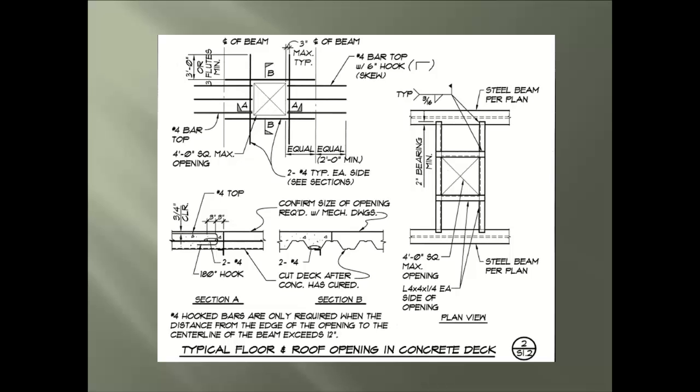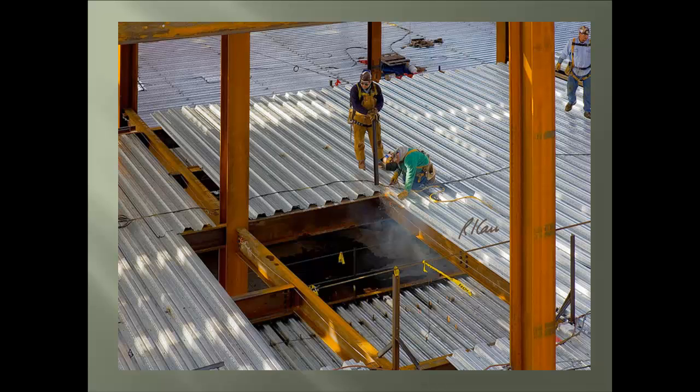First, we see the universal sign for openings through something, which is the X. Next, with this opening, there are the 2 steel beams and the steel angles used to make the actual opening. The next material is the steel decking, and then the reinforcing steel and concrete are added. And with all these components working together, you have a proper opening through a concrete deck that can withstand seismic-induced forces.